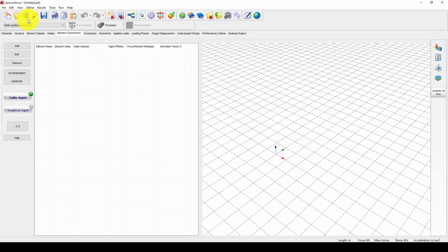Now I can add the bracing in two or three important locations. One is here and one is here in the X, and again one is here and one is here. Now I can go to the 3D, and you can see the model is created like this. So now I want to add some slabs, and here the slab thickness is 150, as before, and it's the gravity load. Adding this one here, here, here, here. Now the first floor is done.